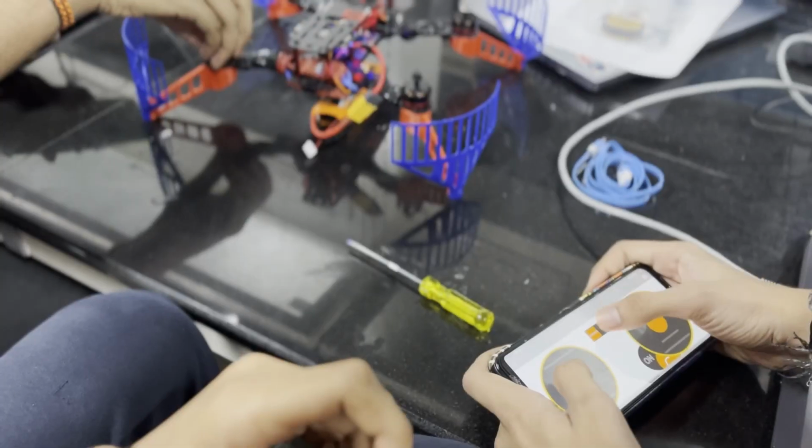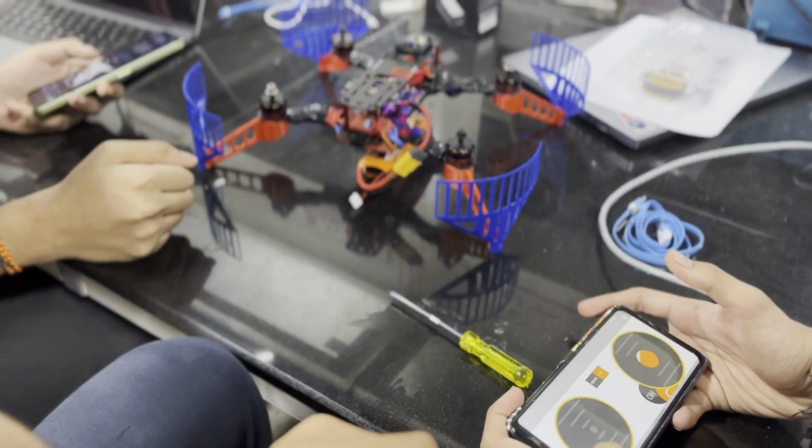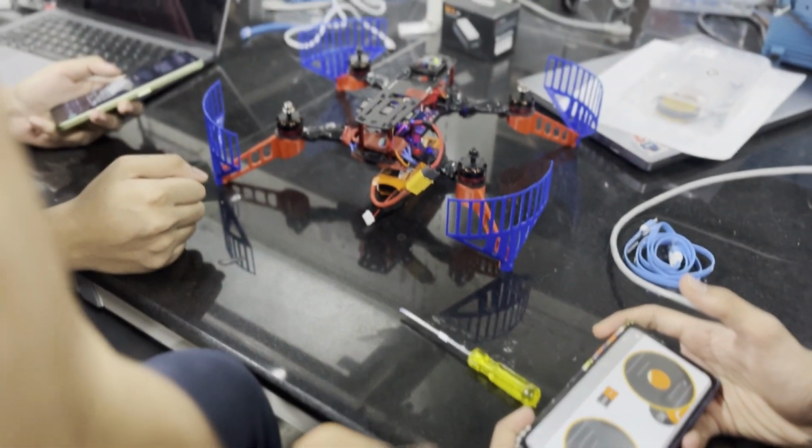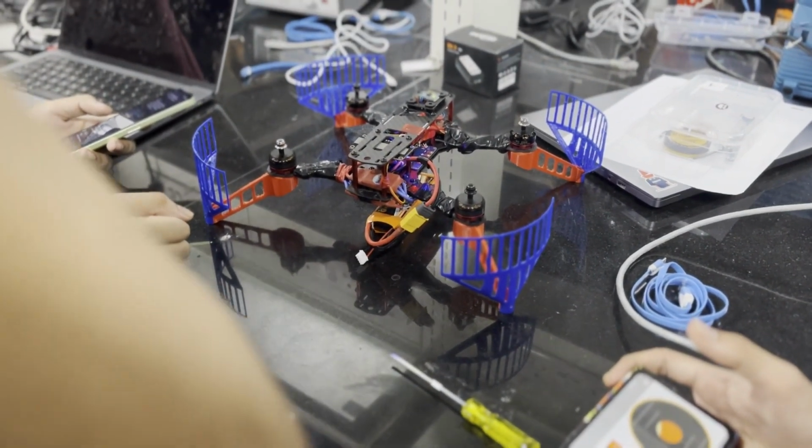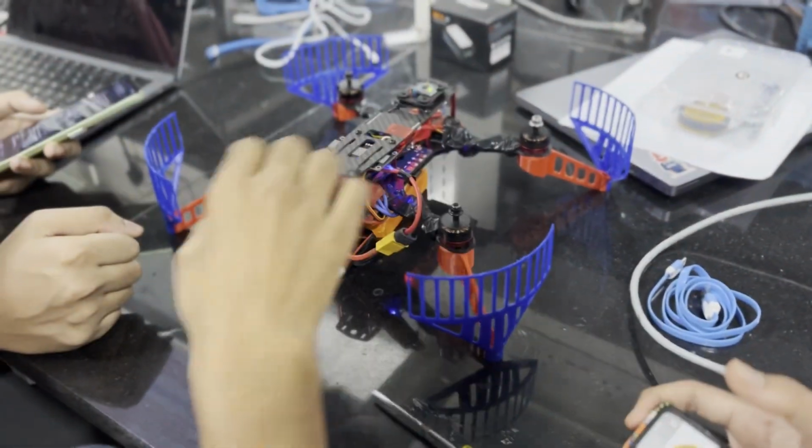In step 3, we uploaded the final flight controller code into the drone, and when the joystick is moved to the bottom left and back to the center, our drone is armed and is ready to take commands. To disarm the drone, move the left joystick to the bottom right.